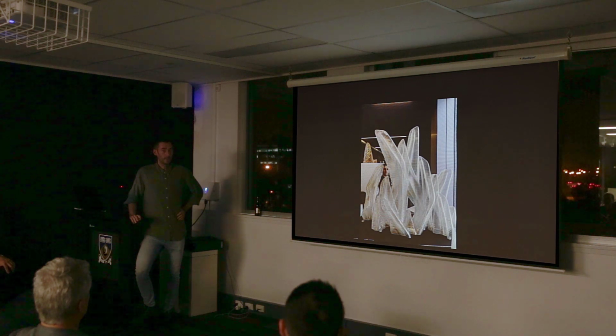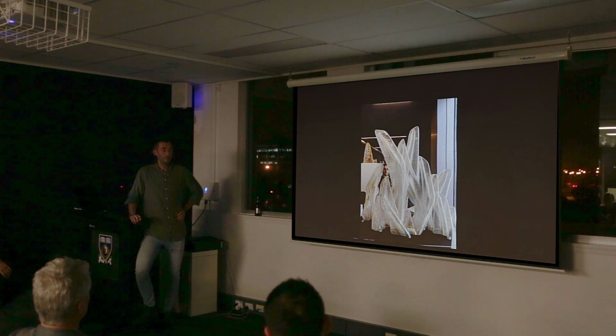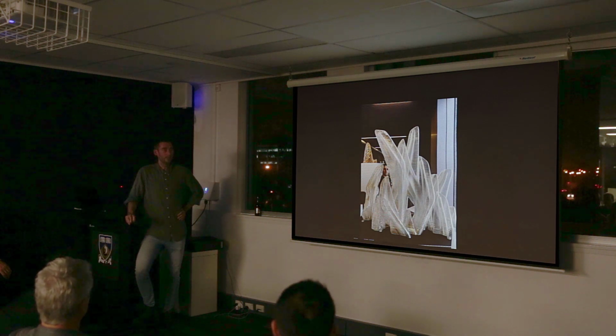You're right, it does become a little bit more of a problem, but that comes down more, I guess, to the structural elements that you try to feed into this. You basically want to figure out a method that takes as much of the stress and load off the formwork and carries that over as much as you possibly can into the structure. And then there would probably have to be a primary structural system that you feed that back onto.